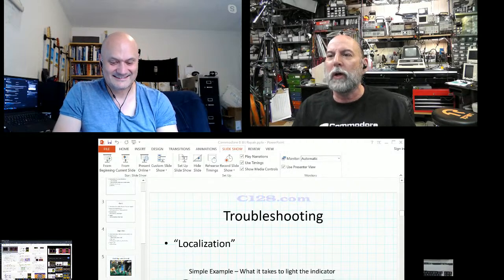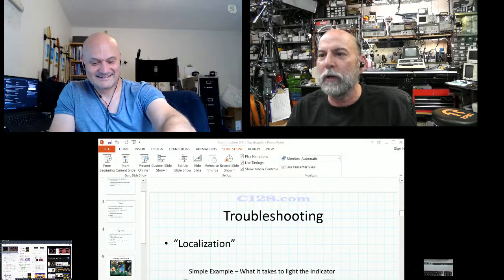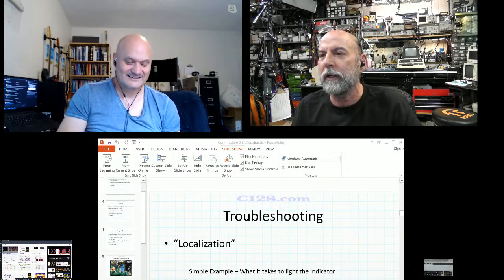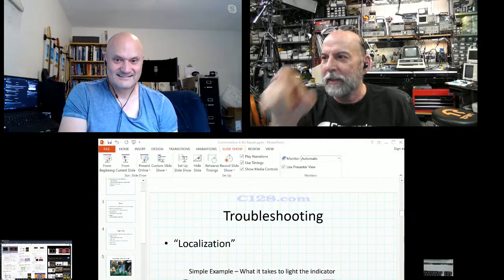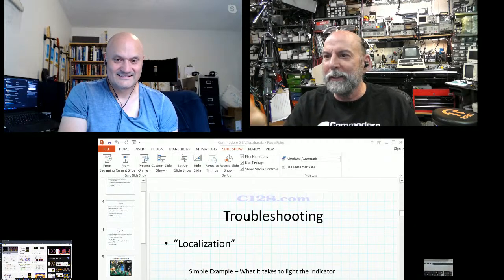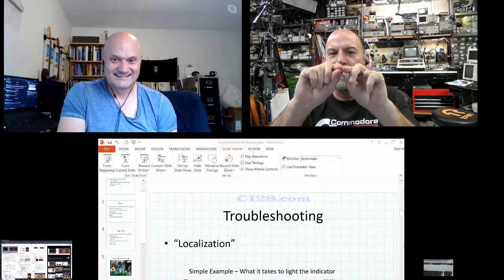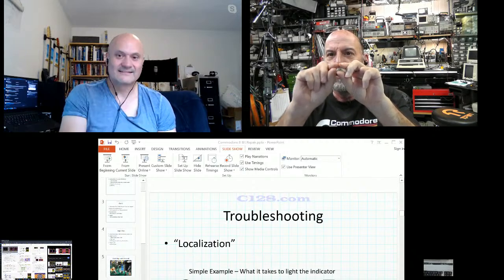One time my boss brought in his stereo, and he was trying to figure out why one channel wasn't working. And at lunch, I was like, well, do you mind if I look at it? And he's like, yeah. He had out the audio test generator. And I just licked my finger and I went, nothing, right? So I back up, and I traced it to where, in the old days, you could have the signal come out of the chassis and go right back in, and they had a jumper between two phono plugs.